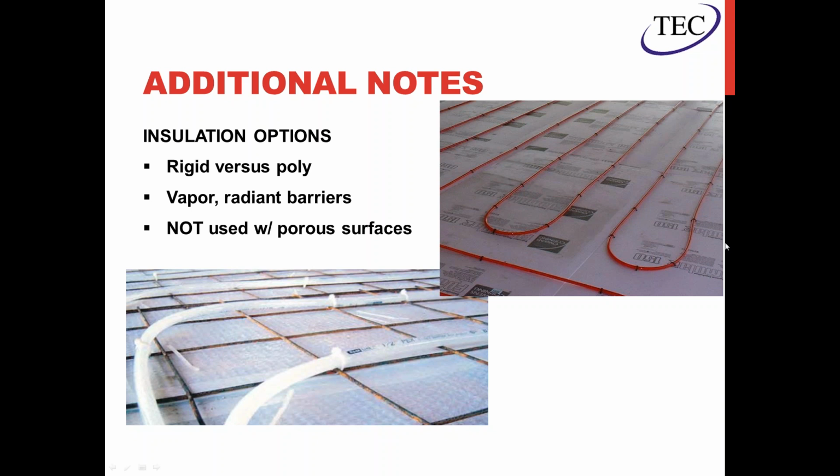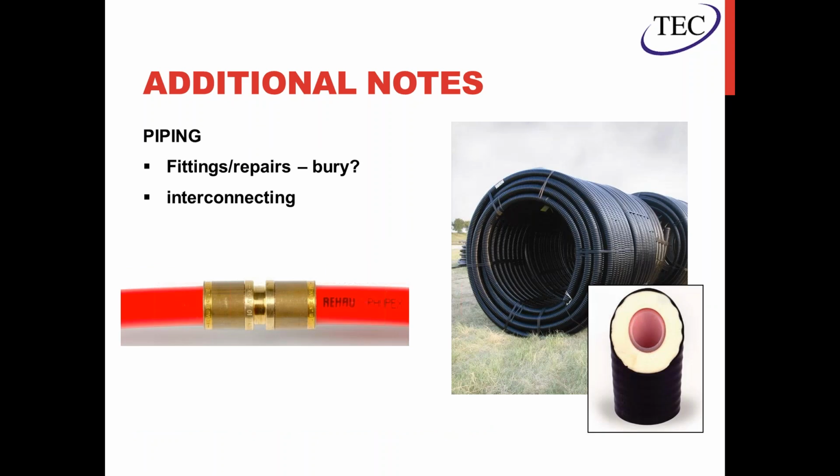There is code in relation to insulation, more geared towards radiant installations, but in either case, they usually just require edge insulation at the slab. So that's something to double check, but usually not a requirement specifically for snow melt.